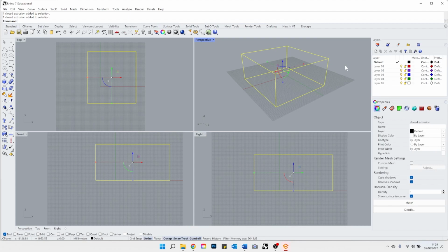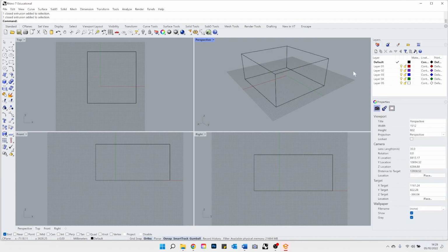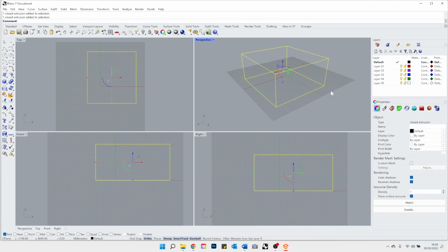If you click anywhere on a gray space around the object, it will deselect it, and straight away the properties give you general information about the viewport and not about the current object. So again, try to create a box or a sphere. If you don't want to constantly be typing box, sphere, or any other shapes, on your toolbar on the left, straight in the middle, there is a box tool.